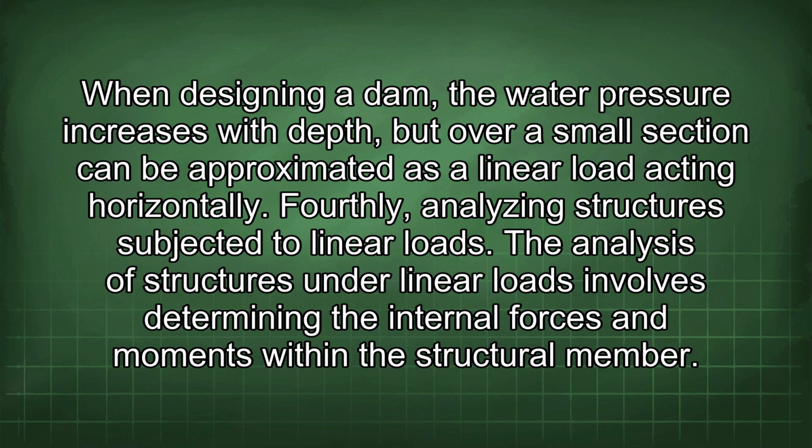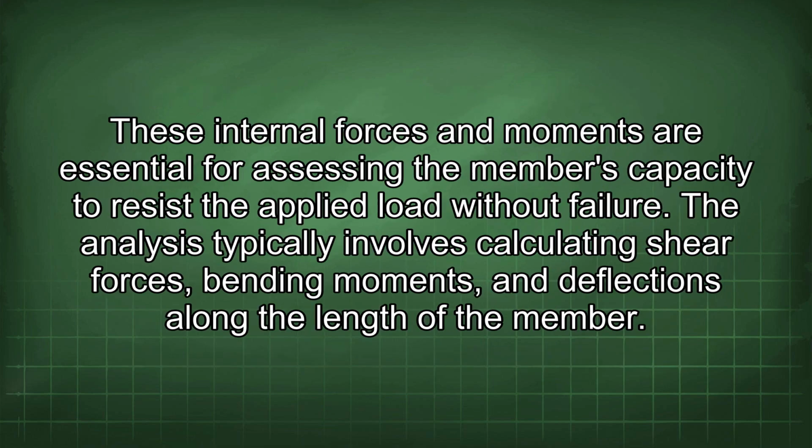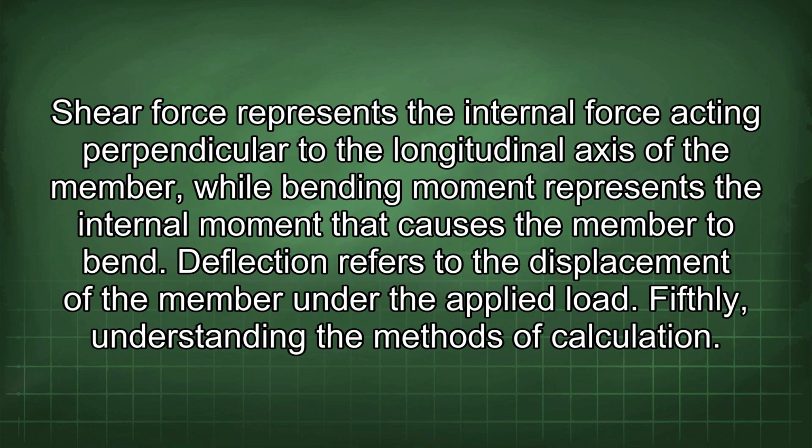Fourthly, analyzing structures subjected to linear loads. The analysis of structures under linear loads involves determining the internal forces and moments within the structural member. These internal forces and moments are essential for assessing the member's capacity to resist the applied load without failure. The analysis typically involves calculating shear forces, bending moments, and deflections along the length of the member. Shear force represents the internal force acting perpendicular to the longitudinal axis of the member, while bending moment represents the internal moment that causes the member to bend. Deflection refers to the displacement of the member under the applied load.